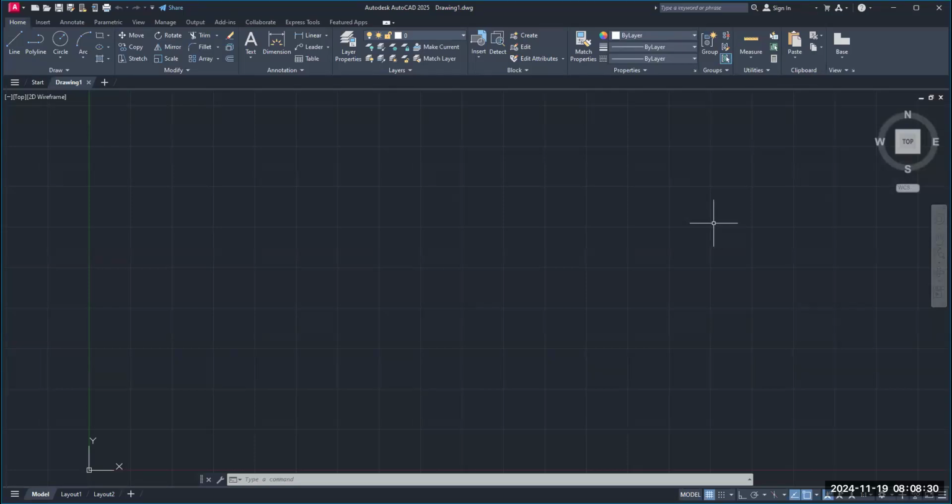Now I want to start with the front view first, which on your drawing is actually the middle view. That's your front view. And then we have the left side view, and then we have the right side view. The left side view and the right side view look very similar to each other, but they're really mirror images, and you have to be careful with the line type because the line type changes from one view to the next.